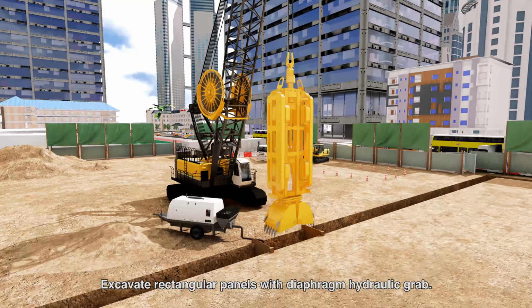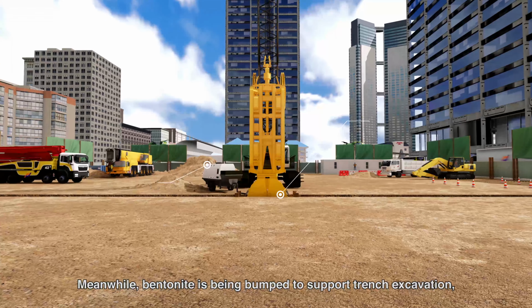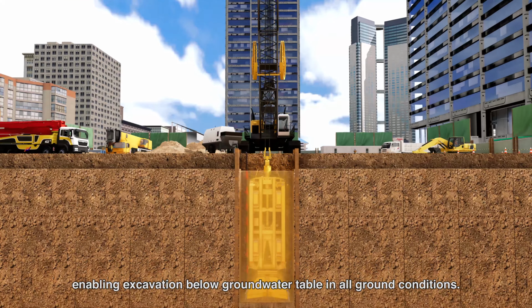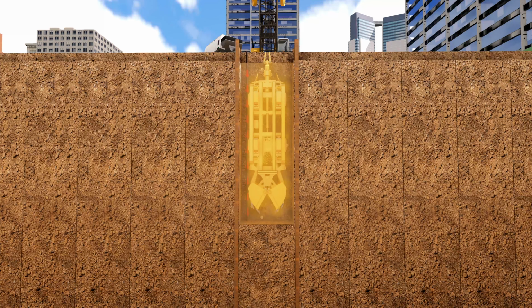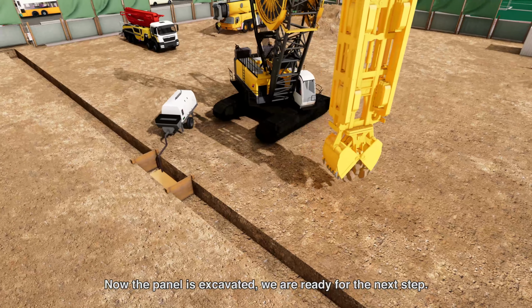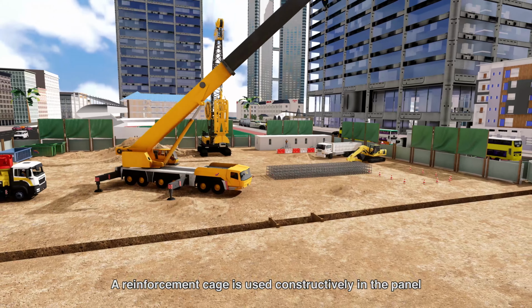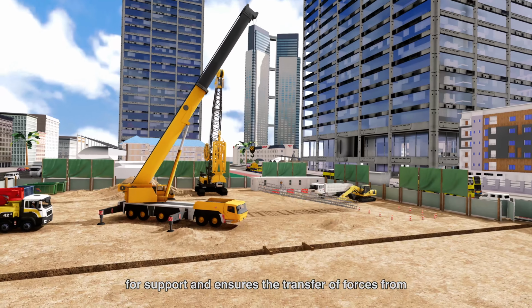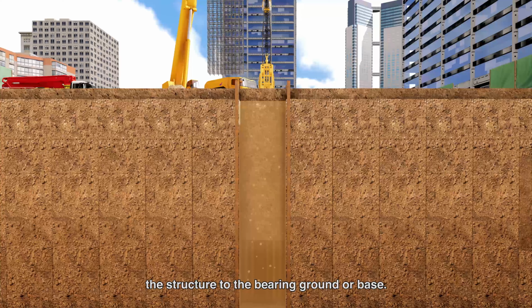Excavate rectangular panels with a diaphragm hydraulic grab. Meanwhile, bentonite is being pumped to support trench excavation, enabling excavation below the groundwater table in all ground conditions. Now the panel is excavated, we are ready for the next step. A reinforcement cage is used constructively in the panel for support and ensures the transfer of forces from the structure to the bearing ground or base.